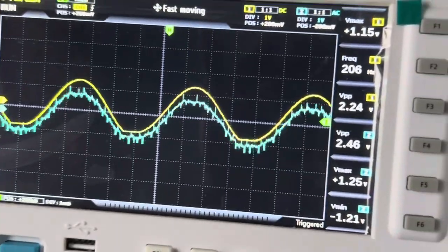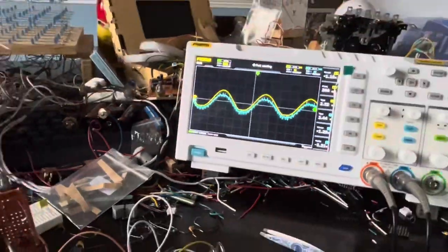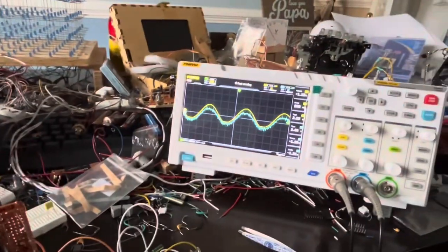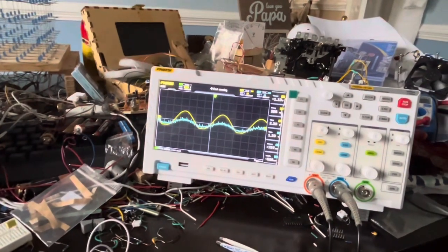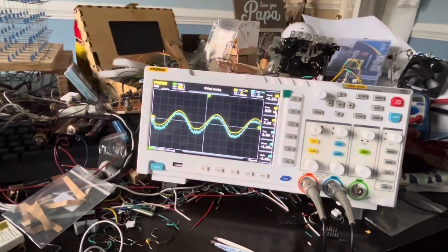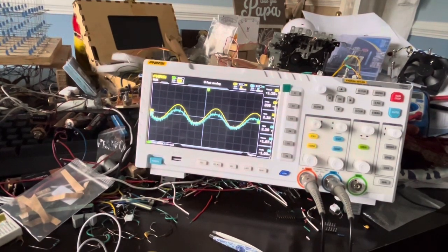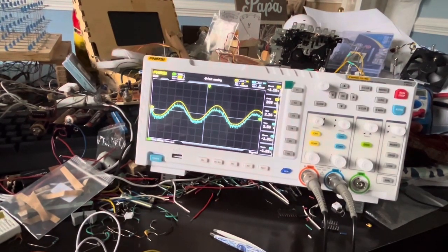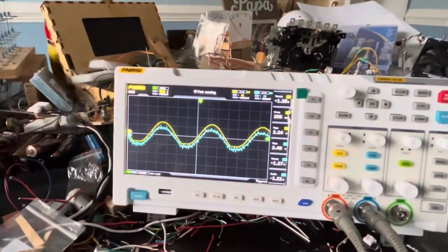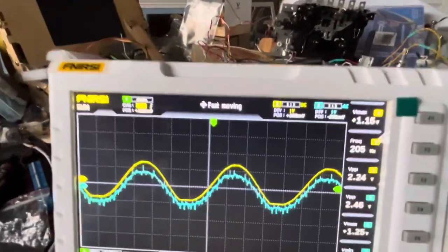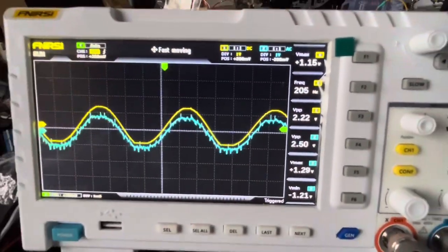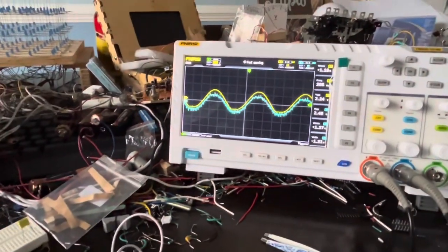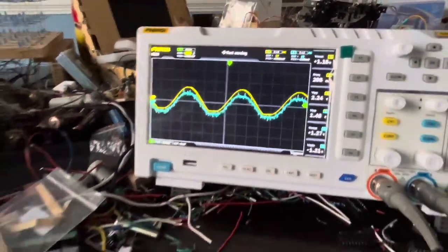So based on this waveform, if I change the threshold here, it's going to provide changes in the waveform. Let's say that I want just a waveform at 2.5 volts peak to peak. Let's adjust it close enough. And 2.48. Now, if you look at the total peak to peak voltage, 2.2 volts there on the input waveform, and it's giving me an output of 2.5.